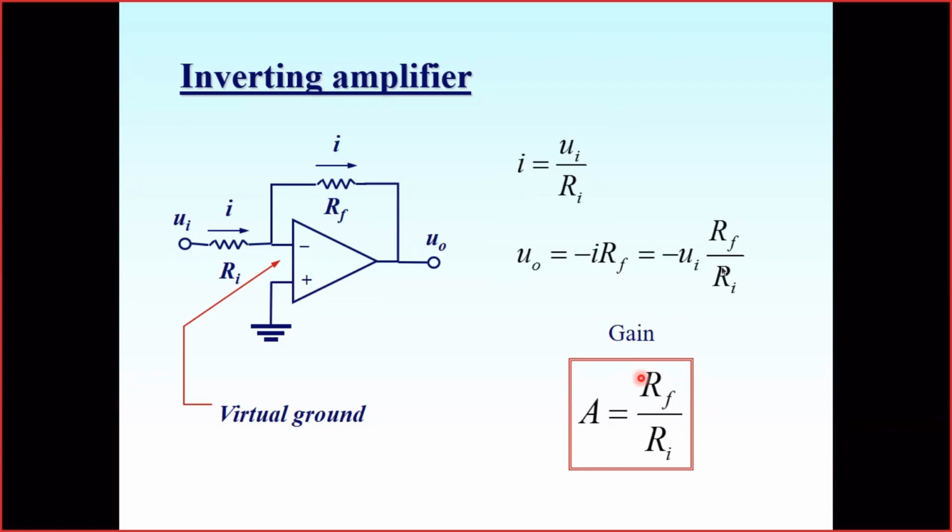Yeah, in theory, but in practice, when the feedback resistor is too high, the output of the amplifier will be subjected to very high noise. The higher the feedback resistor, the higher the output noise. It's just because of the parasitic, fluctuating bias currents that still flow through the amplifier input. They add quite a big voltage drop over a big feedback resistor. So this current may circulate in that way and cause additional voltage drop.